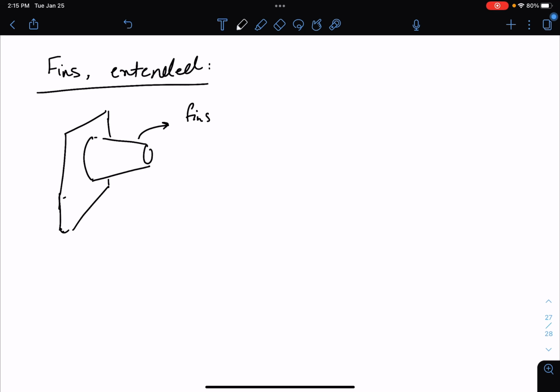Again, here we have the same assumptions. This is one-dimensional heat transfer, no heat generation inside, and so on and so forth. But there is one difference compared to regular one-dimensional heat transfer. The difference is that this surface is exposed to convection, right? All around it, you either have some sort of fluid, a liquid or air, or some sort of gas, which means that you definitely are going to have convection, which means that it is going to be a little more complicated to deal with compared to the regular one-dimensional heat transfer.